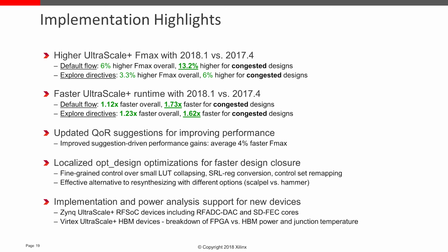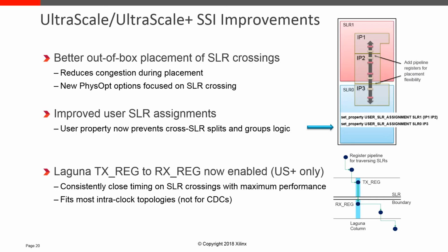2018.1 introduces implementation support for Zynq UltraScale Plus RFSoC and Virtex UltraScale Plus HBM devices. For power analysis, XPE is capable of reporting total power and junction temperature of the FPGA device and the HBM stacks separately. As mentioned previously, SSI devices are prevalent in the UltraScale Plus family.